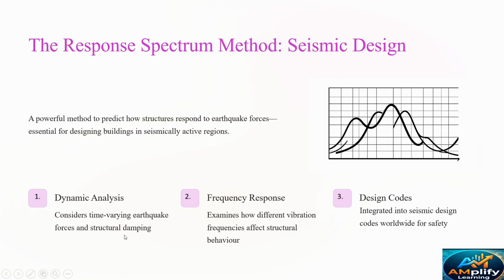What is first? Dynamic analysis. What is dynamic? Dynamic load is a load that changes with time. Dynamic analysis means analysis due to loads which change with time, like an earthquake. Earthquake is a dynamic force; it changes with time. Frequency response is examining how different vibration frequencies affect the structural behavior. That is called the frequency analysis.